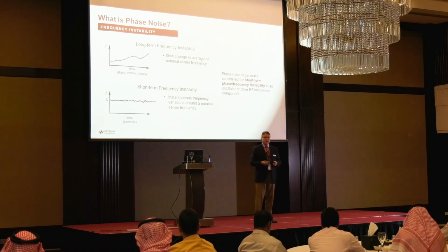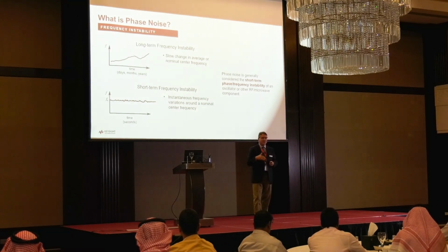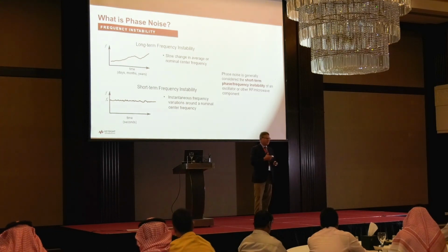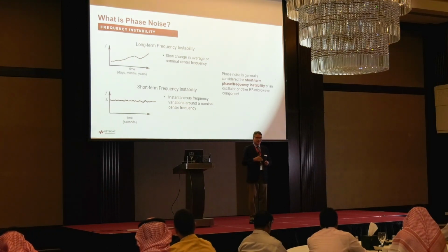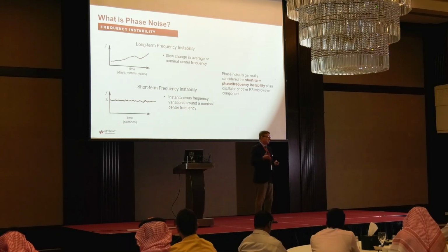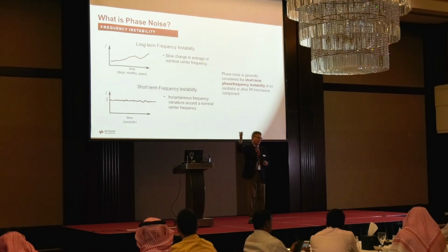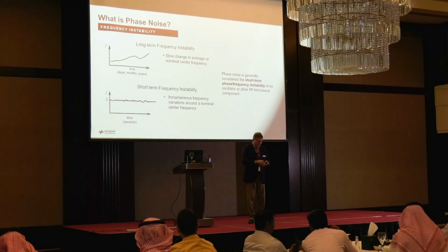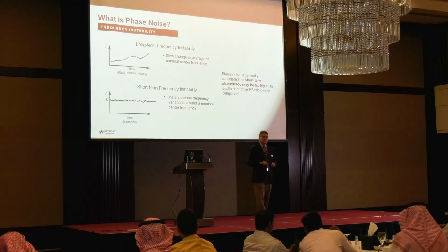of the system. There's also short-term frequency instability, and that is something that we usually look at on an instantaneous basis. So typically non-stochastic processes, noise, thermal effects cause very short-term frequency instability of my carrier signal, and that is what we will focus on today, and that is the type of frequency instability that is associated with phase noise. So long-term and short-term, we will talk primarily about short-term frequency instability today.